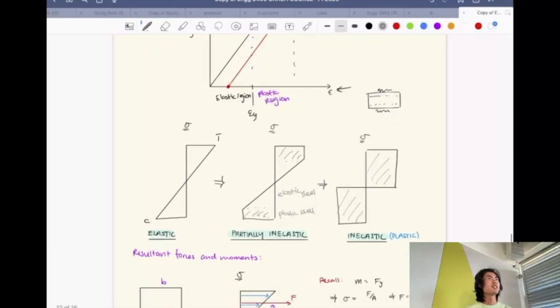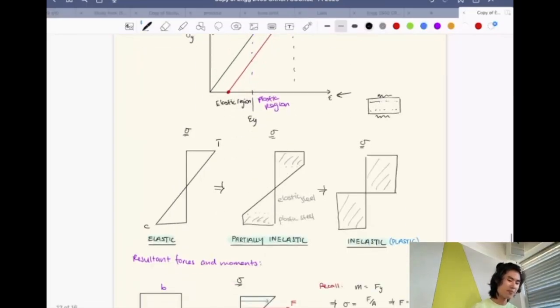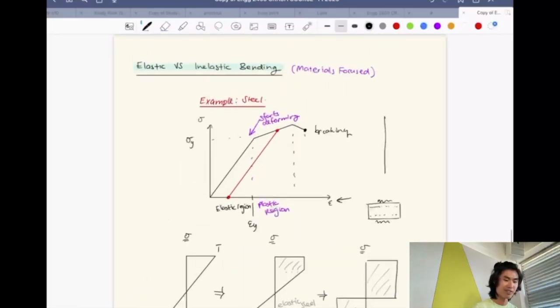With more brittle materials, you'll find that they just fail, and the stress distribution curve can look something like this, and then it starts and stops, and then it will just completely break. So there will be no stress experienced there because there's nothing there to experience that stress. That's a more brittle example. That could be for glass or concrete.